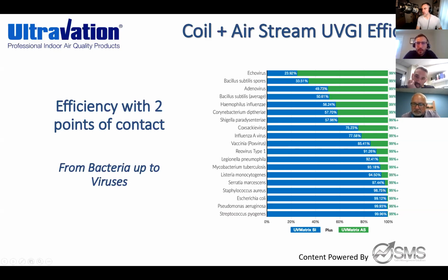This has been a very educational graph for a lot of people who don't understand the importance of combining both technologies and both applications. So we always recommend that you treat both the Airstream and the coil. A lot of people think you can just throw it in the Airstream and you're good to go and not worry about the coils, but the reality is you do get a lot of growth on the coils. They do get wet. It's a breeding ground for bacteria, mold, and a lot of other stuff. And then you do need to treat the Airstream as well.